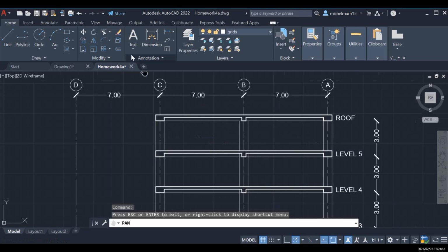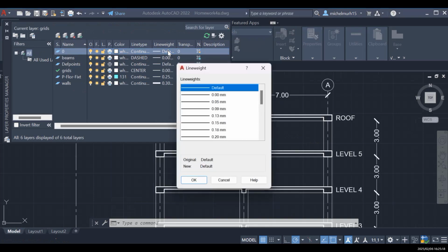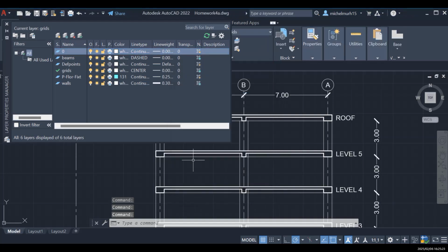So what I'm going to do here is go on properties and change the property from grid to normal. I want my lines just to be normal lines. I don't want them to have any specific line detail. But before I put 0 here, this is the initial properties. It can never be deleted. It can be changed, but it will never be deleted, right? So this is the initial one, but I want to make sure that the line weight is 0. So I'm going to click on the line weights, pick it, make it 0.0, okay? And press OK.